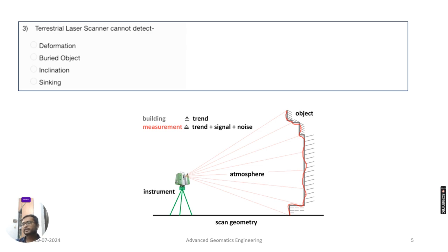And then we will measure these two surfaces which we generated from this terrestrial laser scanner. Then we will get to know at which location it might have bulged out because of the pressure generated due to the water. Like that you can find out the different deformations happening on the dam surface, and then you can suggest rehabilitation methods to avoid dam failure. For that, this terrestrial laser scanner is useful.